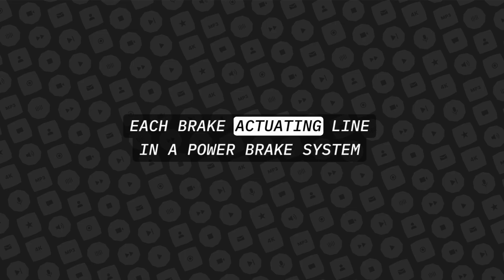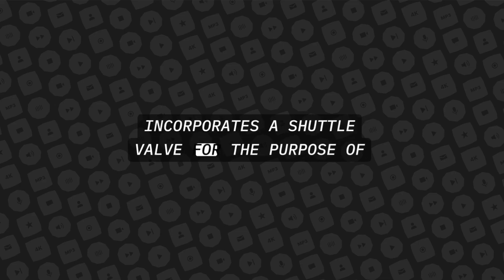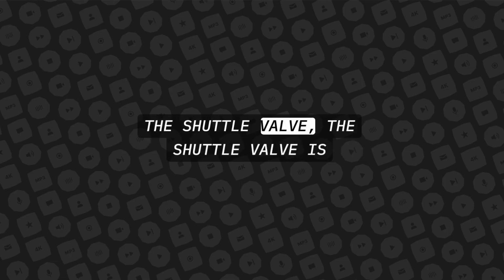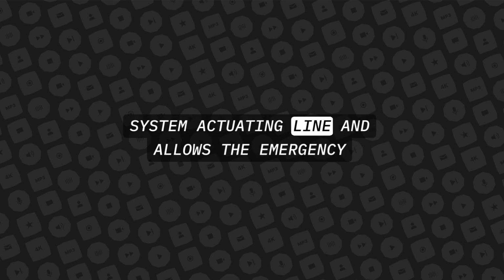Each brake actuating line in a power brake system incorporates a shuttle valve for the purpose of isolating the emergency brake system from the normal brake system. When emergency brake actuating pressure enters, the shuttle valve is systematically moved to the opposite end of the valve. This closes off the normal hydraulic brake system actuating line and allows the emergency fluid to actuate the brakes.